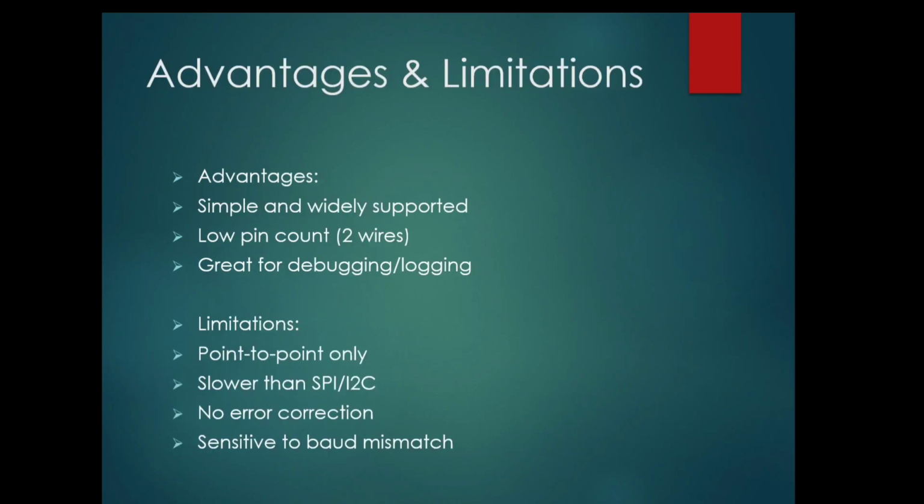There are some advantages and disadvantages of UART. As an advantage, it's simple and widely supported in embedded systems, and it uses only 2 pins, RX and TX, and 1 pin for ground. Generally we use it for debugging, flashing, and logs.